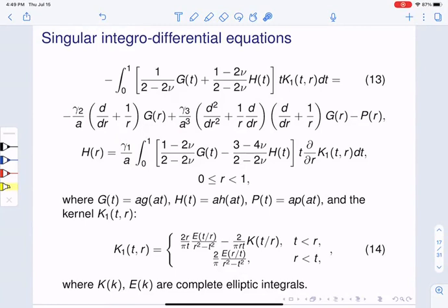If you look at the real values computed for different materials, we can see that when the scale goes to nanoscale, so A is again 10 to 100 nanometers, these parameters are relatively big, so surface has influence on your material behavior. If you go to macro scale, these parameters become so tiny that you just don't see the influence of surface. This theory works for nanoscales.